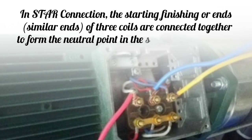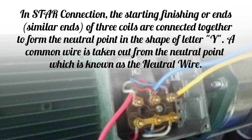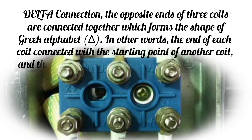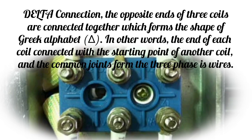Star. In star connection, the similar ends of three coils, starting or finishing, are connected together to form the neutral point in the shape of the letter Y. A common wire is taken out from the neutral point, which is known as the neutral wire. Delta. In delta connection, the opposite ends of three coils are connected together, which forms the shape of the Greek letter delta. In other words, the end of each coil is connected with the starting point of another coil, and the common joints form the three-phase wires.